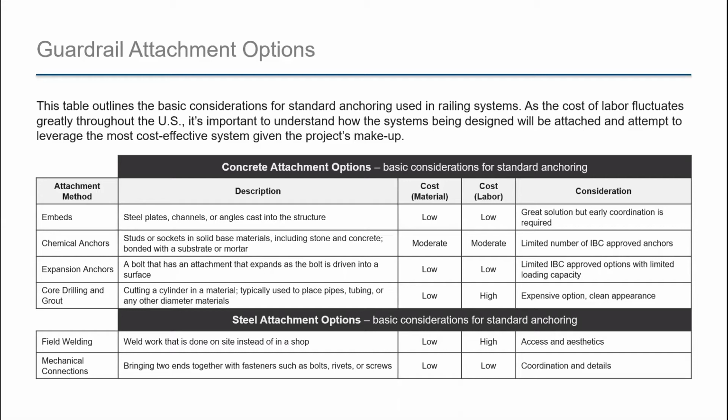Most concrete slab constructions or steel structures can easily accommodate typical interior railings. However, for many exterior railings that will accumulate wind loads, thorough consideration should be given to the attachment detail in the design phase, as early as possible. As with member sizing, design teams should consider loading, geometry, and material when considering anchorage options. Again, it's suggested that a competent professional be engaged early in the process when you're talking about attachment design, to avoid potential problems later in the life cycle of a project, which become much more costly. I'll turn it back over to Shelley to finish up the presentation now.